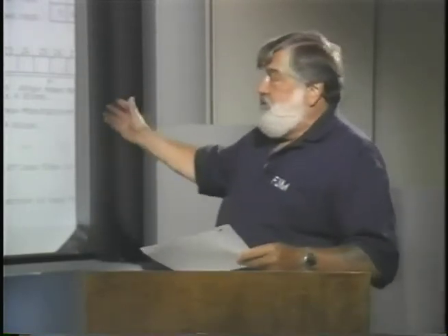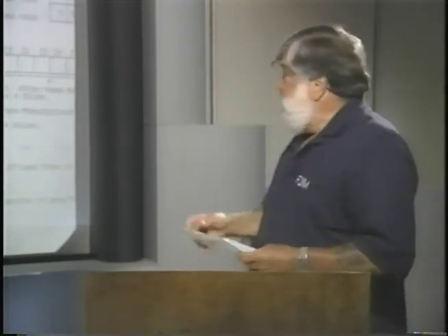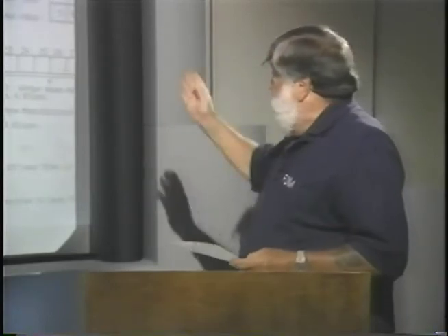and look at the descriptions and devise your own part number and your own description and see how much of a change you would have to make to these source documents, which hopefully may help you to shorten the time span for bearing part numbering generation. And in this case, again, we have the second field, which is 56. The first field is always 04 for bearings. And for pillow block roller bearings, again, we have the same succinctness of the development of the description.